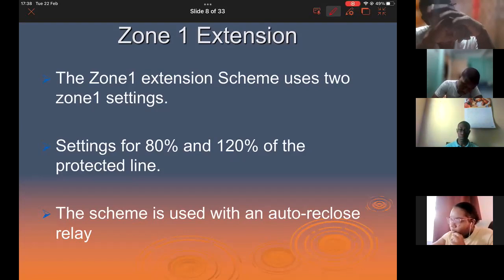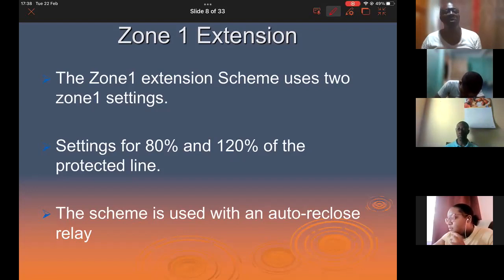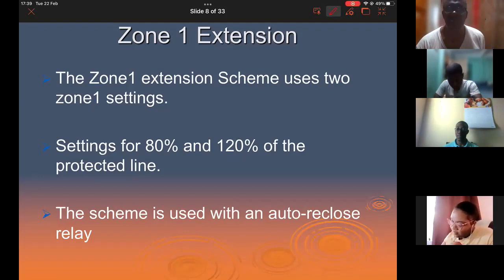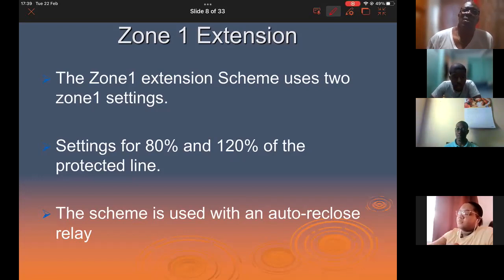So next time you pass a substation, I don't think they have removed them, you will see microwave antennas on top of the relay house. So that's what they used to use in the past. But of course, microwave is somewhat unreliable because it has to operate by line of sight. And to achieve line of sight in Jamaica you're dealing with a fishbone. You have the range of mountains running right down the center of the island. So you will have challenges going across the island. But when we get there, we'll talk about that.